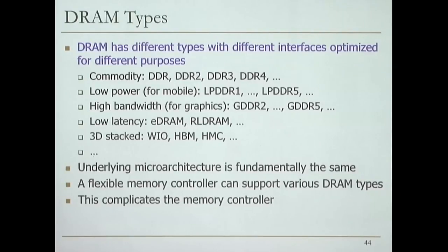So we're going to start thinking about why memory controllers are hard to design. One of the reasons is you need to support multiple of these. You don't always have to, but if you don't, then your flexibility reduces. So you have a clear trade-off between flexibility and the support you have for different types of memories. For example, this one has only LPDDR, and I cannot plug in something else to this. This also has LPDDR, and I cannot plug in something else. And LPDDR is slow compared to some other memories. It's difficult to support all types and upgrades.